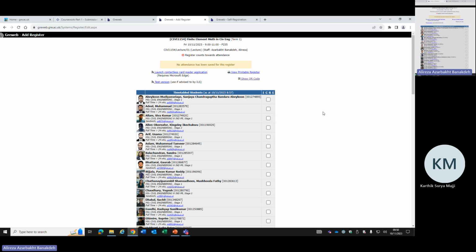know, we have hinges here, and because we have hinges, if you close the rotations, this element can rotate. It doesn't make a difference. You can close all of it. The vertical should be free. It's roller in vertical. So if translation along Y should be free, yes. Everything is restrained, but the vertical.